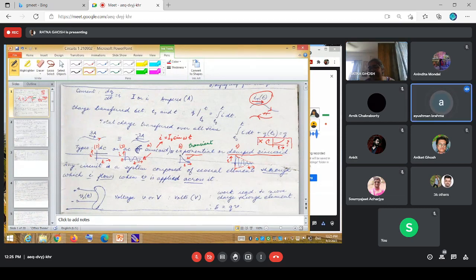But ma'am, we see this type of graph in the forward bias, reverse bias in the diode. Forward bias in the diode is a different scenario altogether. I'm talking about an exponential rise, I versus V. I drew a reverse exponent dying out to zero, but what if this just kept on increasing? In a reverse bias diode, there is automatically a saturation, so it will never go exponential ad infinitum.